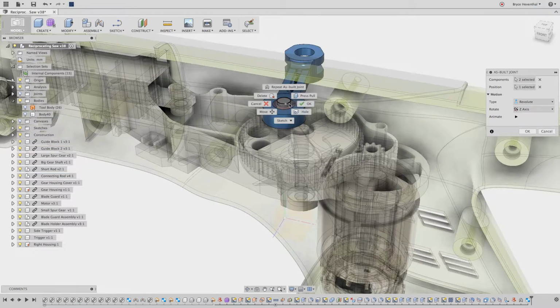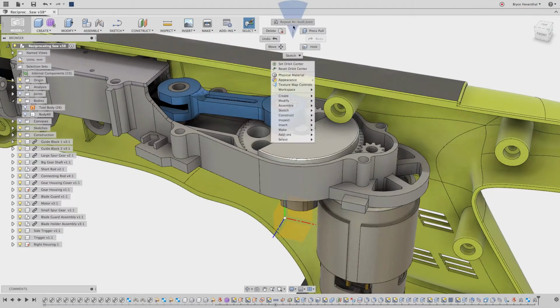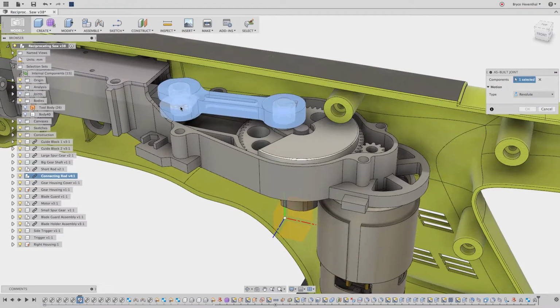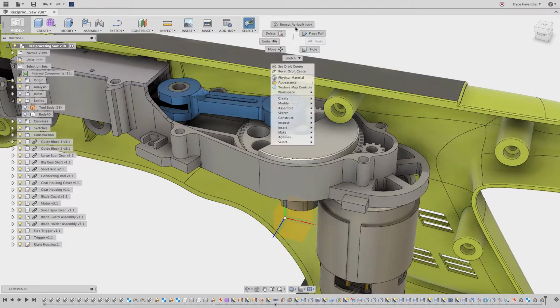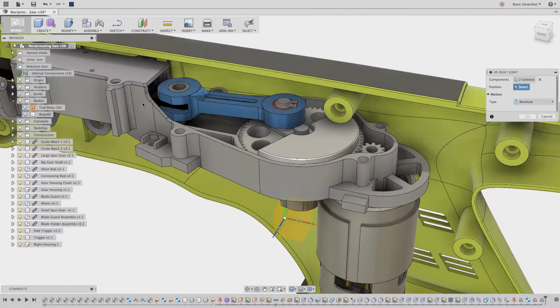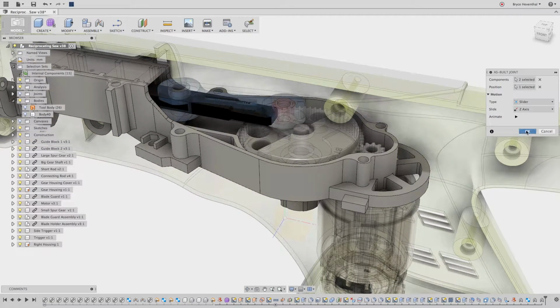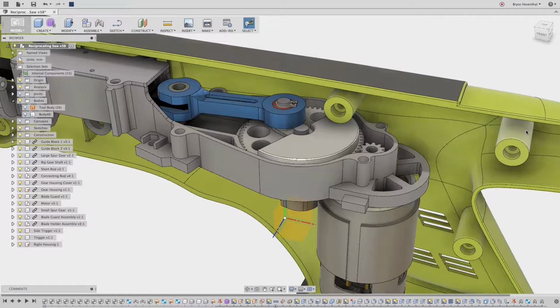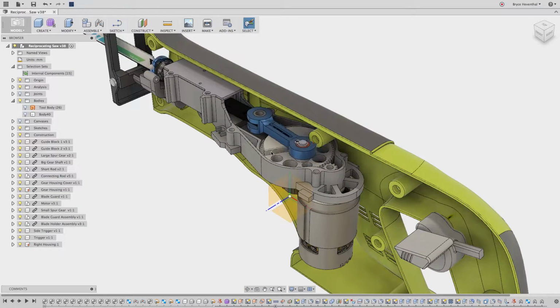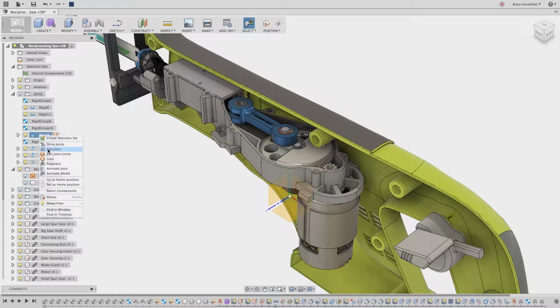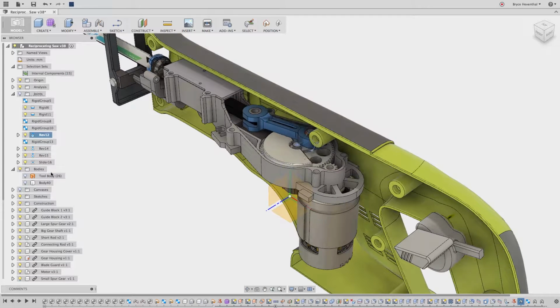In traditional CAD, when mating or applying constraints, usually an engineer is trying to lock down the 6 degrees of freedom, 3 translation and 3 rotation. This usually takes 2 to 3 constraints or mates to get the desired motion. In Fusion 360, we apply one joint. We lock all 6 degrees of freedom down and change the joint type to get the desired assembly motion. This will help designs get assembled faster and behave more robustly when design changes are made.